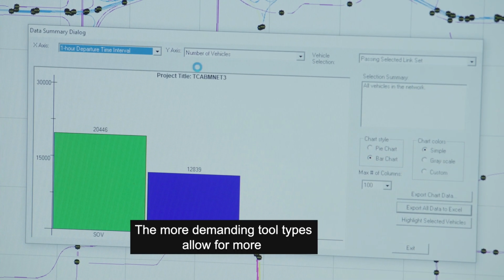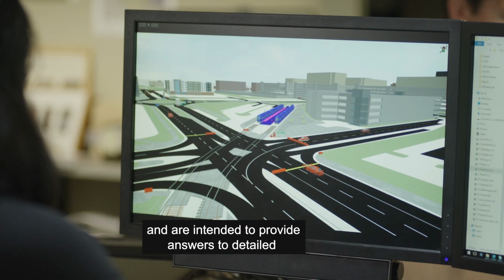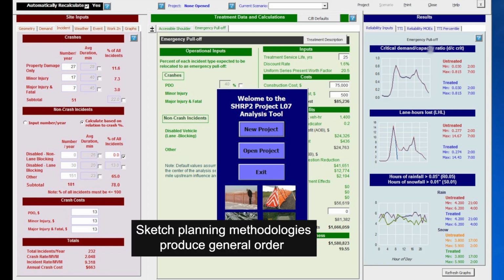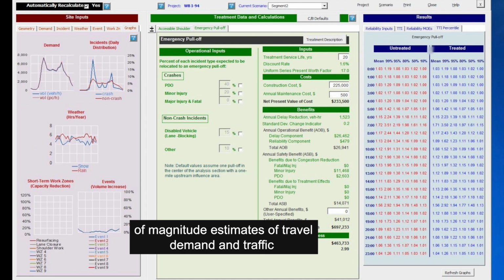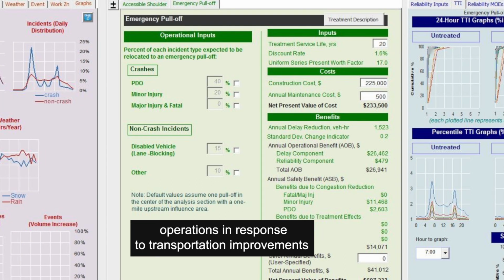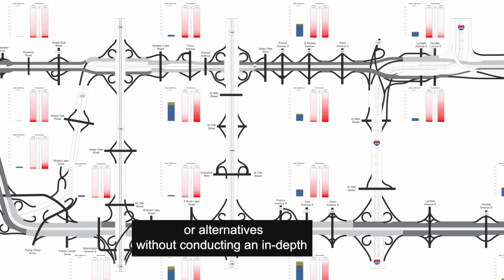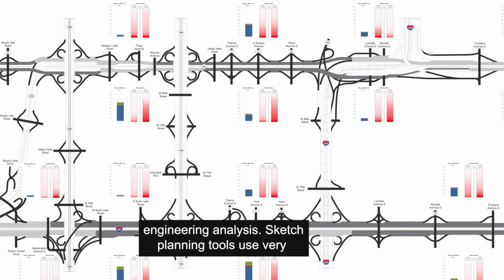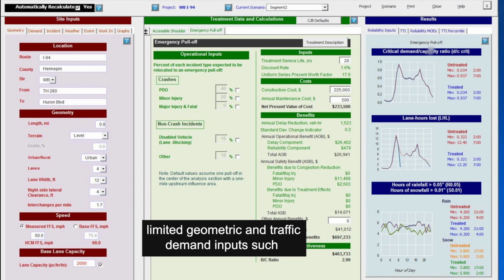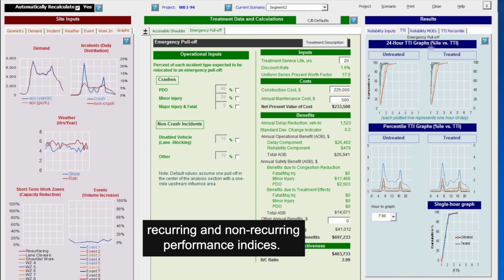The more demanding tool types allow for more comprehensive reliability results to be developed and are intended to provide answers to detailed design questions. Sketch planning methodologies produce general order of magnitude estimates of travel demand and traffic operations in response to transportation improvements, allowing for the evaluation of specific projects or alternatives without conducting an in-depth engineering analysis. Sketch planning tools use very limited geometric and traffic demand inputs, such as demand to capacity parameters, to predict recurring and non-recurring performance indices.